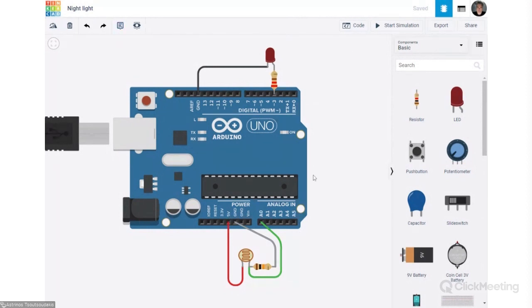An Arduino can be powered in different ways. You can power it and upload any code you have created by using a USB cable. But you can also power it by using Vin, to which you can apply any voltage which is at least 6 volts.